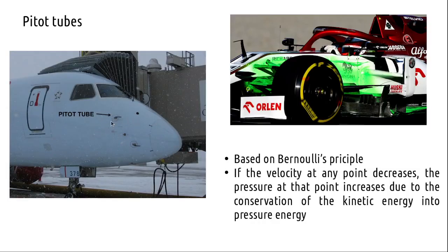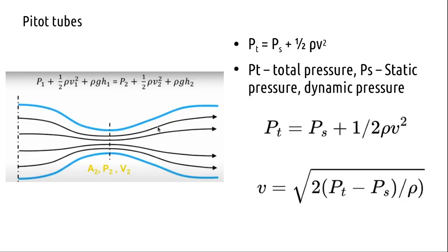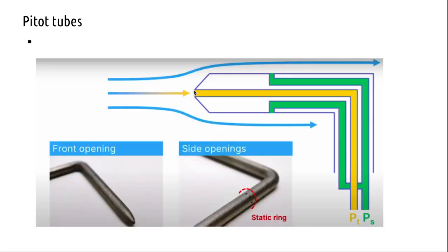When it faces the air, the air becomes standstill at this point. This point the air becomes a standstill. So this is a static pressure. And these are connected to sensors, transducers internally. This particular chamber is connected internally to pressure transducers.